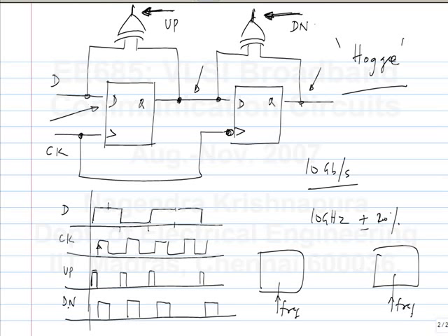So what you do first is this whole loop works like a regular phase lock loop. It simply uses the periodic input and brings the frequency close enough to the data frequency. Then you switch over from that phase loop to this loop. You keep the VCO and the loop filter and everything the same. You simply switch the phase detector and you switch the input. Instead of being the periodic signal, it will be the data. So then it will lock to data. It has come close enough to the data, and then you lock to data. That's what you normally do.